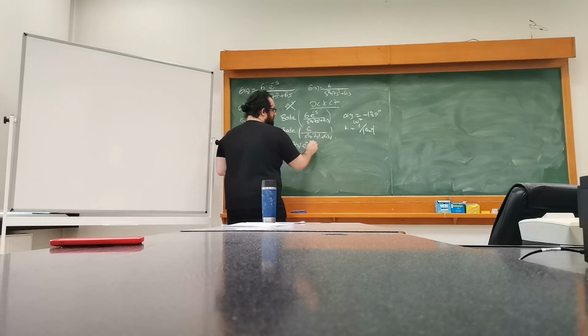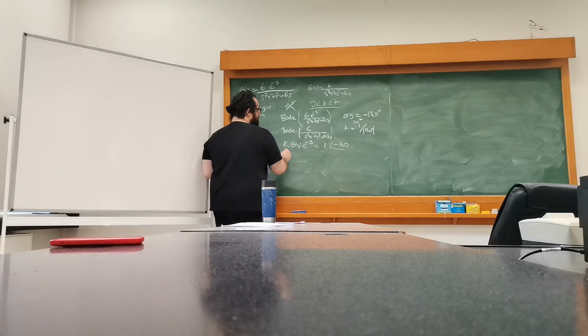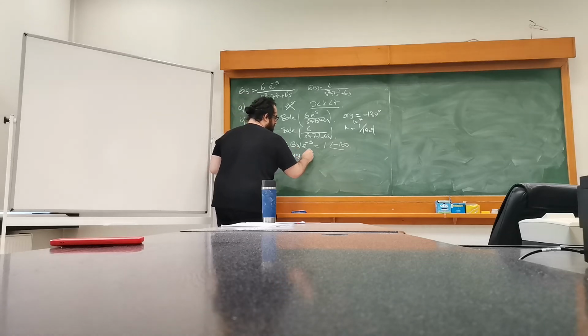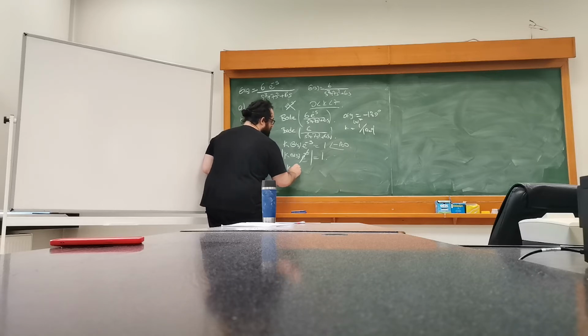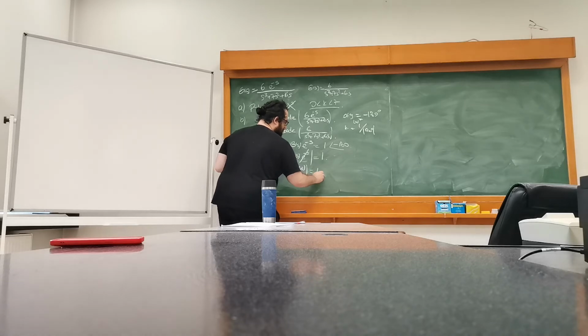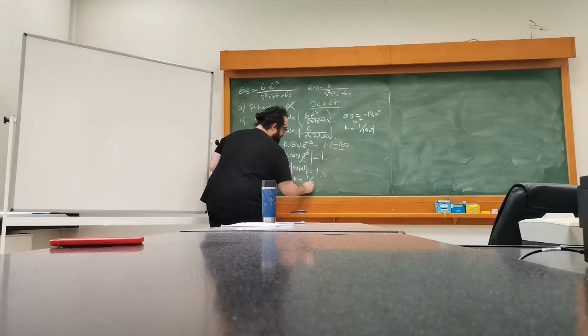And we're basically looking for magnitude 1 and minus 180 degrees. And as we thought previously, the delay has really no effect on the magnitude. Therefore, we can just set it equal to 1, take the inverse, and use the same value.